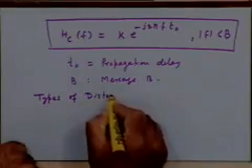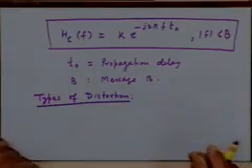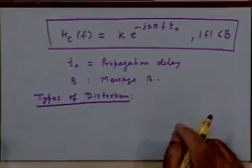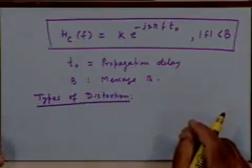Incidentally, these kinds of distortion that I'm discussing here, we also refer to them as linear distortion, right. Linear because they are arising from the non-ideal characteristics of a linear filter, which is being used to model the channel. The ideal characteristics are, it should be a linear filter, but besides linearity you want the magnitude transfer function to be constant.